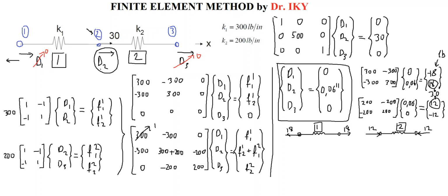If you collect them together, I will give you for the total system minus 18 pounds, or left hand side. Our second node, we have, this is the reaction. These are right hand side, and this is just because of the free body diagram of the node 2. Because of that, you will write the directions of the forces opposite. It means this is also 12, and we have got in total right hand side 30 pounds. This is our final definition.